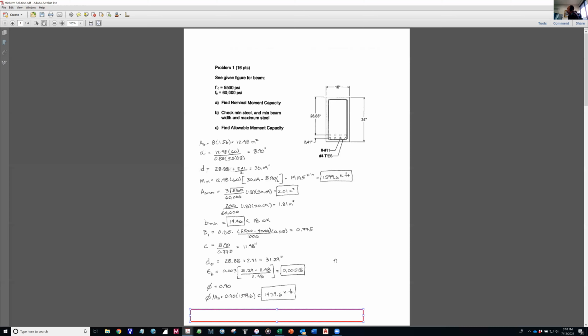Now, there are probably, in fact, I've been told definitely, examples where I had 2 rows of steel and I didn't do it that way in my example. It's easy to forget that little nuance of the code. So you're being a little bit conservative when you just use d instead of d sub t, and it's kind of more of a practice that we do. But this answer is the technically correct answer that follows the code to the letter.